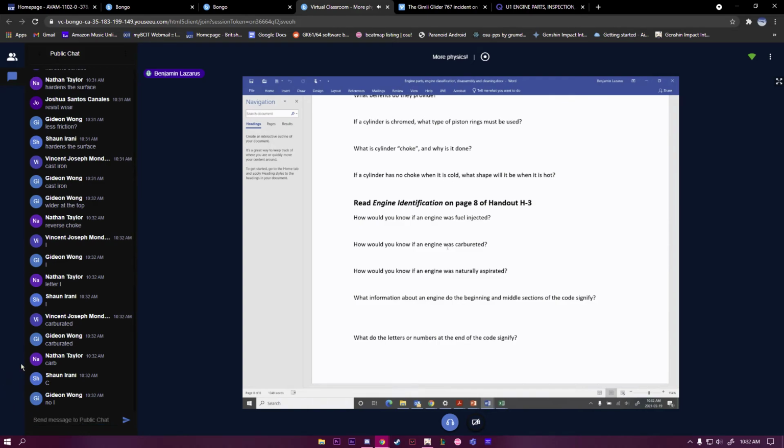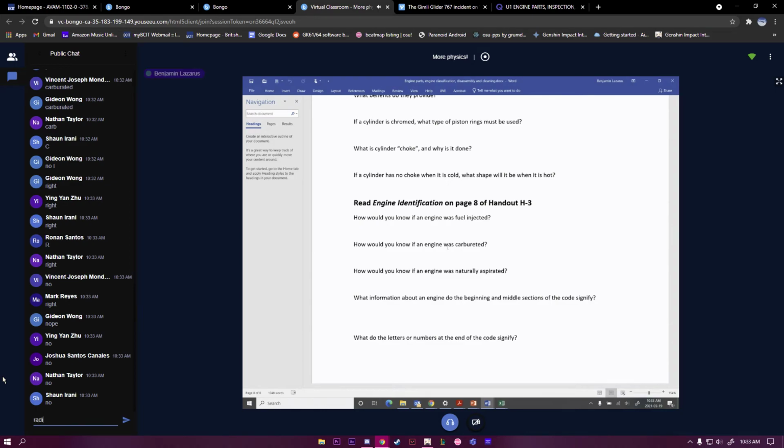How do we know which way the engine rotates? Which way do most engines rotate, right or left? Right. So do we ever put an R in the engine? No. Actually, we do. What does an R stand for? Radial. Okay, so if it's not a right-hand rotation engine, it must be a left-hand rotation, and we'll put an L. If it is not a fuel-injected engine, it must be carbureted, so we don't put anything. It's kind of assumed to be carbureted unless you get that magic I, right? The BMW 320i with a fuel-injected engine, right? Put an I in there.